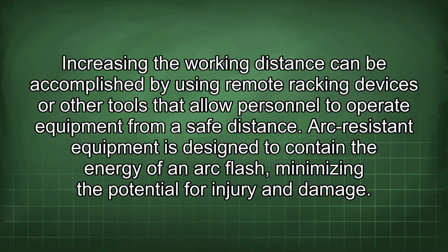Increasing the working distance can be accomplished by using remote racking devices or other tools that allow personnel to operate equipment from a safe distance. Arc-resistant equipment is designed to contain the energy of an arc flash, minimizing the potential for injury and damage.